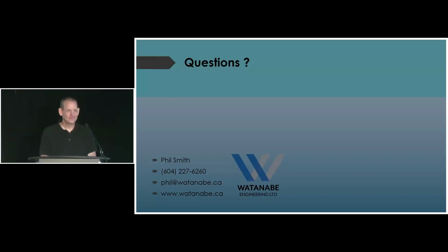Have you found any problem with radar next to seaways? We had an issue with a radar type device, and when the big yachts went by, it was disrupting the radar. Okay, I haven't seen that. Do you know what type of radar it was? We just took it out and went back to a float switch. How long ago are we talking? This was 3 years ago.